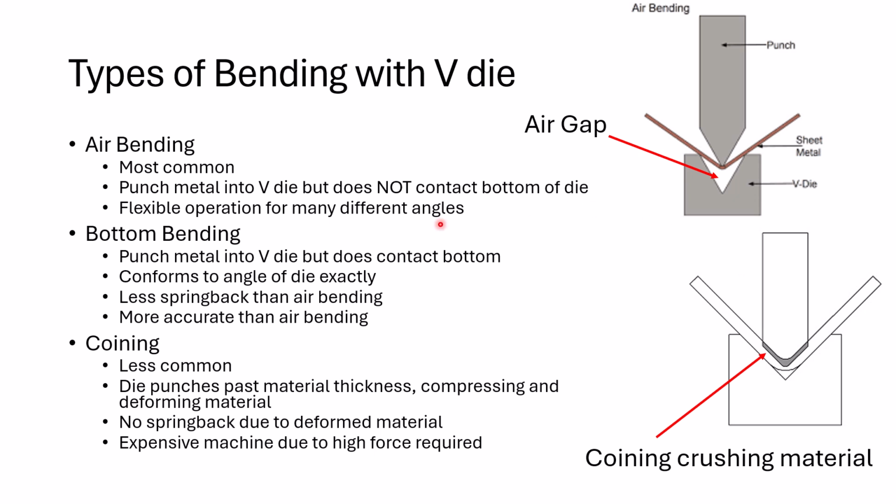So what's going to happen? One thing that's important is it's flexible. So you'll start off with this bar right here. It's completely flat. Then they'll punch it down. Maybe they'll move this thing down just a couple thou and move us into a small angle, maybe 1, 2 degrees. And the farther and farther you go, the more and more you're going to bend this angle right here.